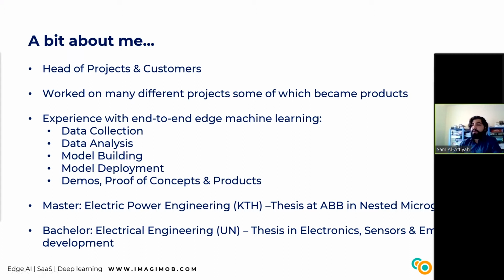And what we mean by end-to-end is that we do the whole chain of the development. So we plan the data collection and we actually collect the data. Then we perform the analysis and the model building, so getting to understand the problem and how to solve it. And then eventually we deploy these models onto edge devices, normally microcontrollers, and the most common one that we work with is the ARM-M4. So we work with demos, proof of concepts, and actual products.